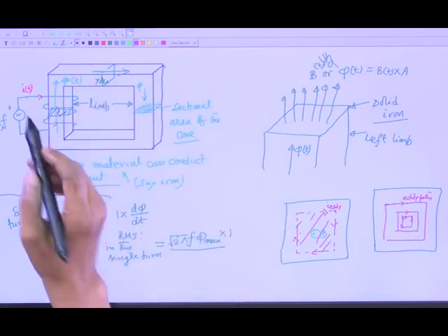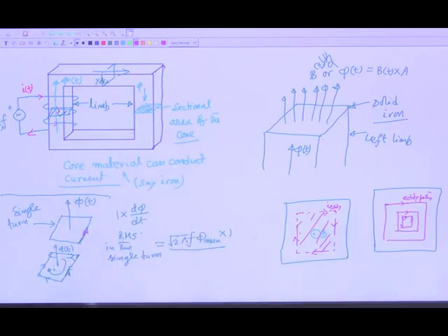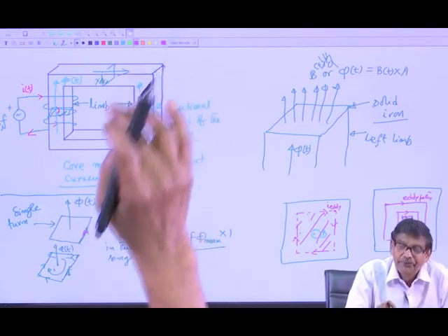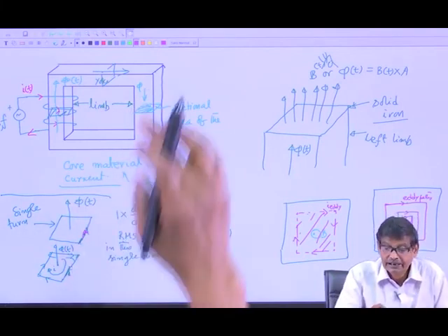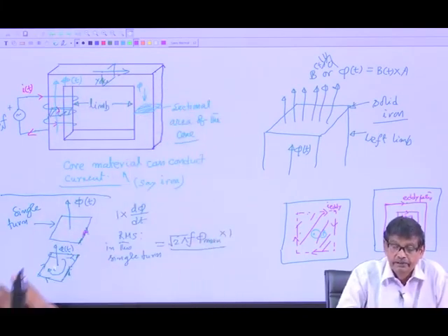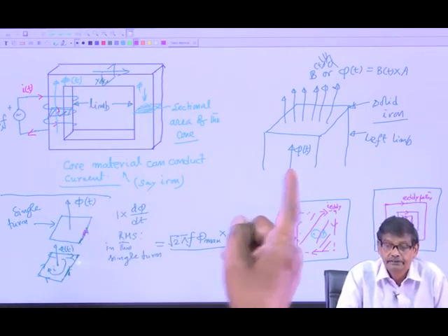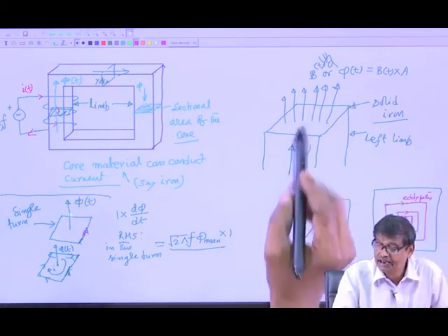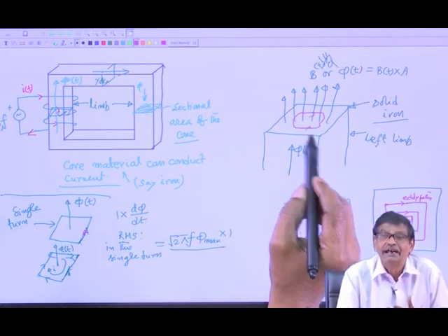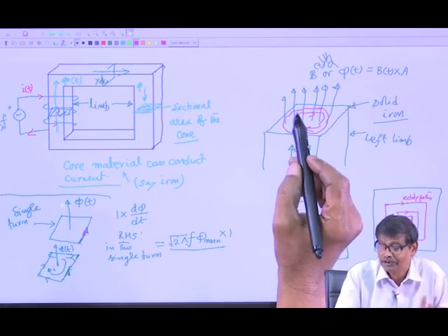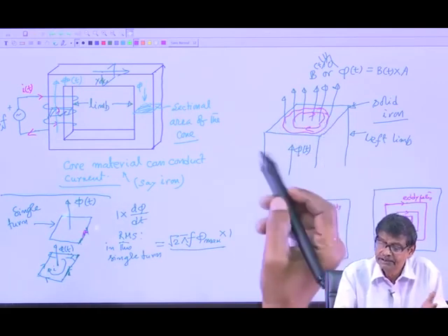Power loss in a transformer also takes place in the winding resistance, coil resistances R1, R2, whenever they carry current. That is incidentally called copper loss. That we will discuss in detail, but what I am telling is, if you touch the core, it will become hot. Why will it become hot? There is no electrical connection between the coil and the core, which is made of say solid iron. One of the reasons is that through the sectional area a time varying flux exists, and you choose any conceivable closed path, there will be induced voltage and eddy currents. It may not be rectangular, any arbitrary path loop. Now, if I say okay, the path is like this, will there be some eddy current like this? Yes, it will be.